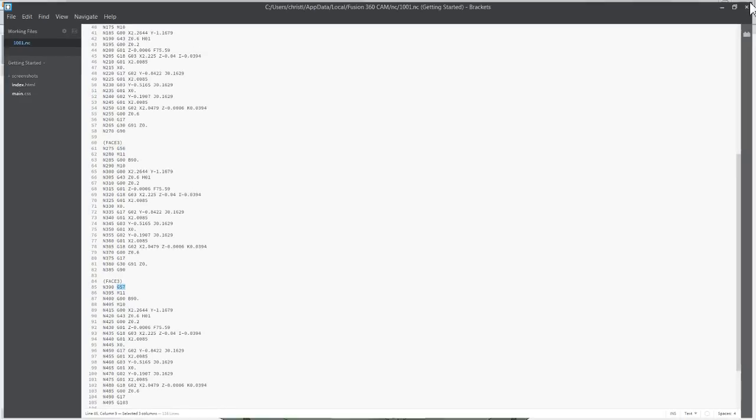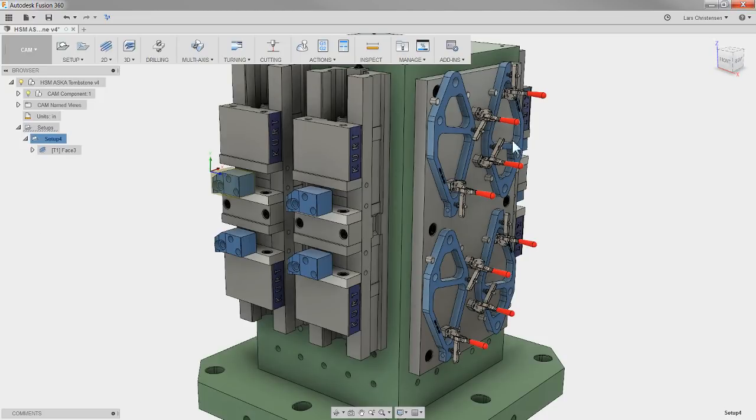What that means is that in the CAD and CAM, I only programmed one part, but when I post the code out, I get 4 duplicates with the work offset changing, in this case G54, G55, G56. What that means is when I get out to the machine, I will just pick up each corner on the 4 sides and put in G54, 00, G55, 00, G56, and G57, and that way I can duplicate it.